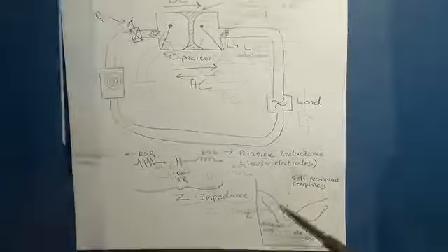That is our dielectric, and that's where we're getting our loss. So that accounts for the first part. But as it starts speeding up, that effect drops off because we now have movement. We've got over the inertia of trying to move this thick bellows, or the dielectric. Then we hit our sweet spot, where the impedance drops to a low point, and we hit our self-resonating frequency.